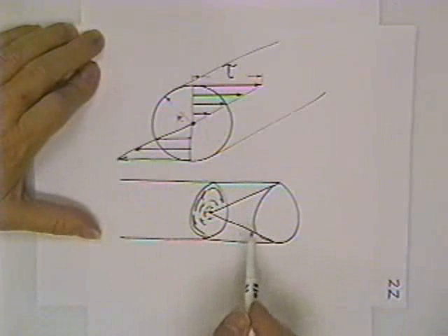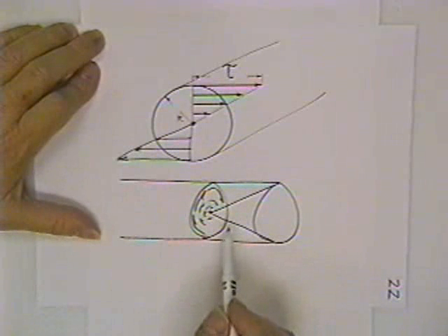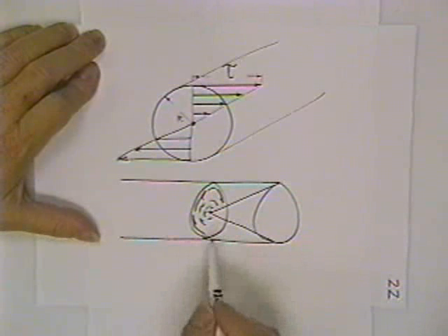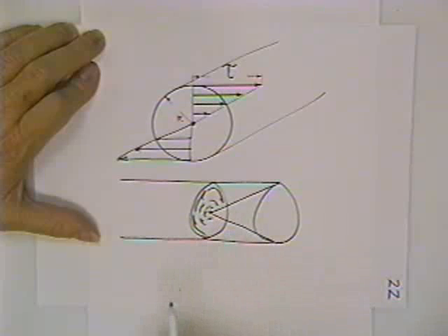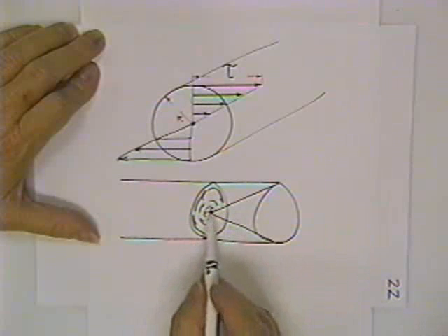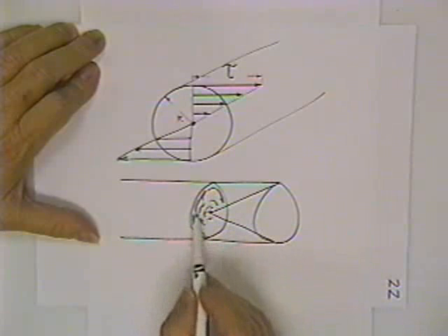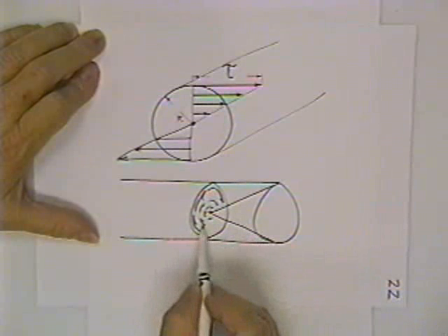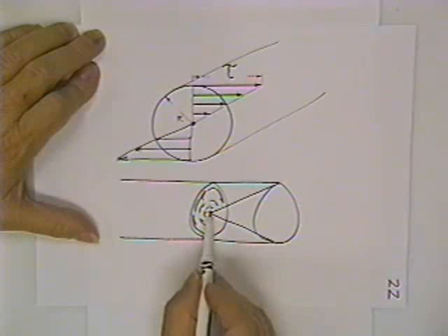And let me mention, it's really important that you know how these stresses are acting on the cross-section. There are a lot of good questions that can be asked. Just where does the maximum stress occur? You know the equation, you know it's TC over J, but you don't really know where it is or what happens. These will help a lot. You'll notice that on the surface face here, I put big arrows on the outside. That's because the shearing stresses are very large. You'll notice then the arrows start to get kind of small. You'll notice in the middle the arrows are tiny.